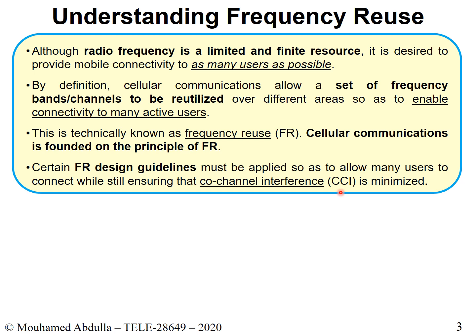Now, when you have frequency reuse, you will essentially be required to form certain clusters of cells. So I'll show you some examples of cell clusters. So this is one cell cluster. Essentially, you have one base station, so you have an eNodeB here. This is the coverage of it. And we said we're going to use hexagonal shapes because that makes analysis easy. And if you need to understand why hexagonal, I made a full lecture to give a sense of why we use hexagonal. So that's considered one cluster. The size of the cluster is 1, and in the cluster there's just one cell.